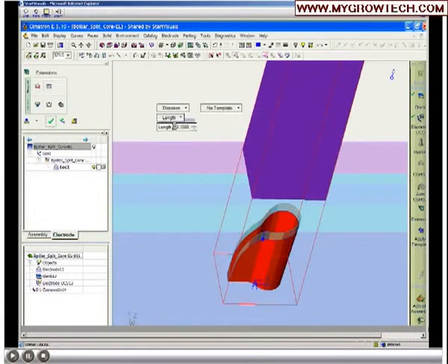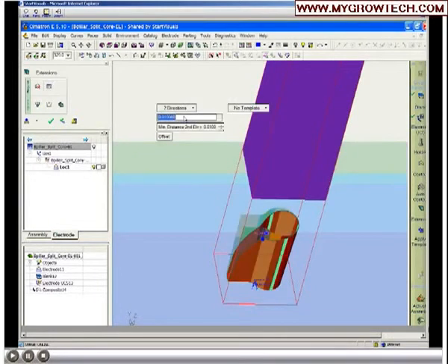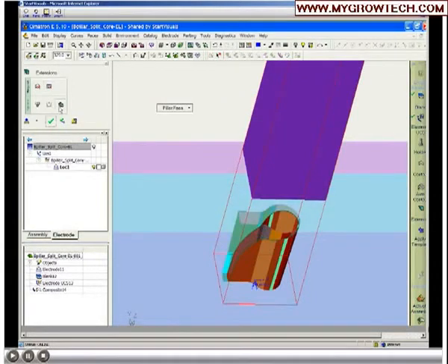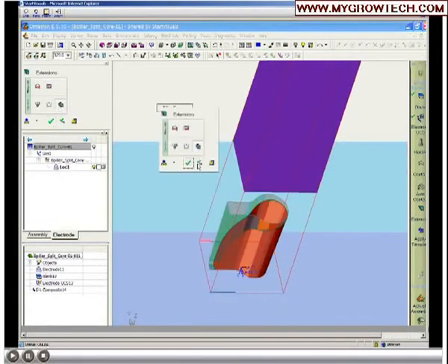The other option is to drive it in a specific direction, so that's what it would look like pulled straight up in Z. The option I'll use here is to drive it tangent in two directions, so we get a nice looking square corner. Let's say we go 50 thousandths up, 50 thousandths out the side, and then we'll close that side off with a filling surface. So there I've got my first extension built.